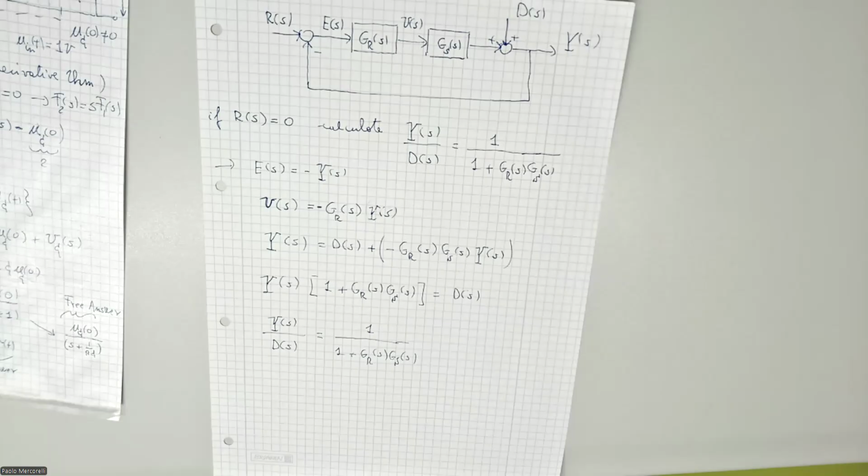The concept of linearization is an important concept. Very often we apply it in order to use the tools of this part of the course. I can use exactly, or more or less, these tools here, or at least the transfer function, everything which we know, because we are considering basically a linear system. This means we will see how we can approximate the nonlinearity using Taylor. I would like to tell you this because you know about Taylor from math. Taylor expansion, Taylor approximation, but we will do it at the end.